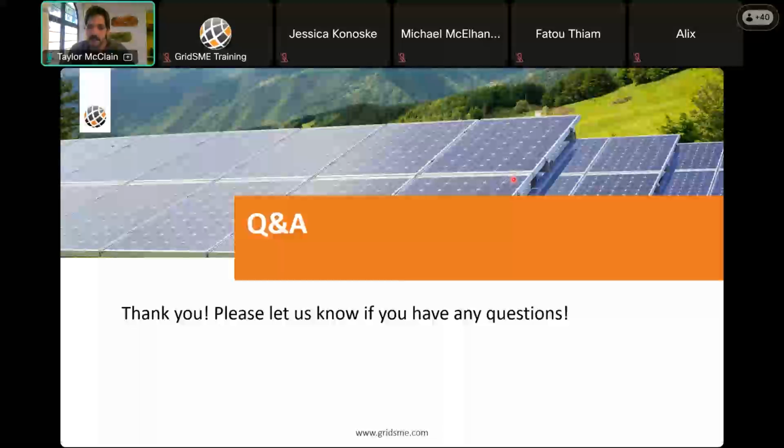And these folks will record the data of the facility responding to real world events, to signals sent to the power plant controllers. And they will record the dynamic response of these units. And then, after a facility is operational, they will model this facility exactly as all the equipment is, find out what the dynamic model parameters should be, and then start comparing the power flow dynamic attributes to the SCADA data that was recorded during the testing.